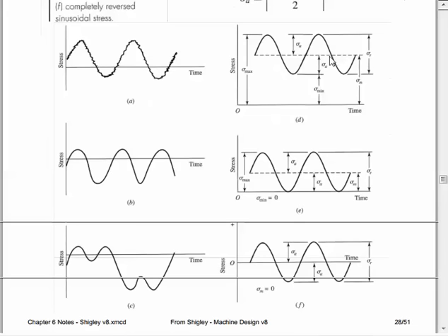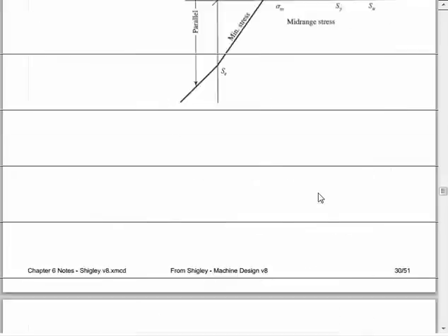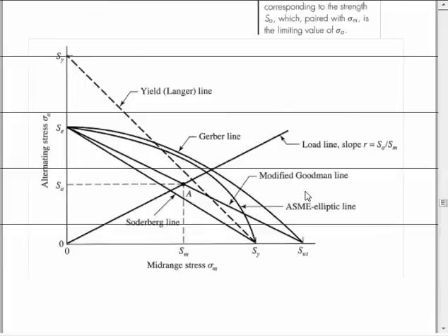Okay, this would be a stress that has a sigma amplitude of something and a sigma mean of something. If we let this amplitude get smaller and smaller, our stress state simply becomes a straight line at the mean location. And a straight line at the mean location basically means static loading, no fluctuation left because we sent that to 0, static loading of some moderately high value. Where do we fail when we have that kind of static loading?